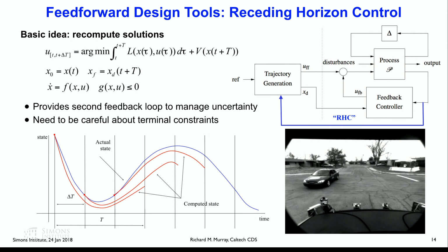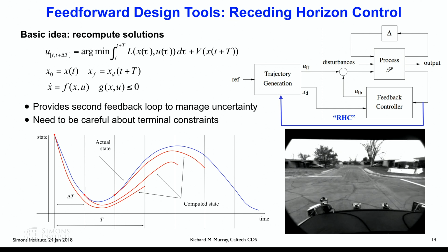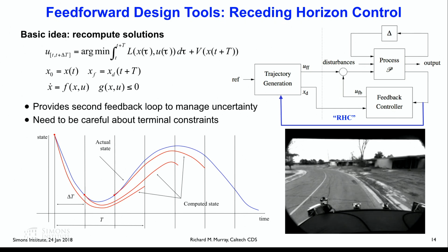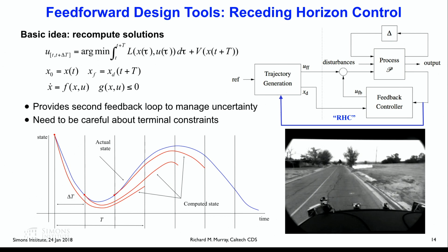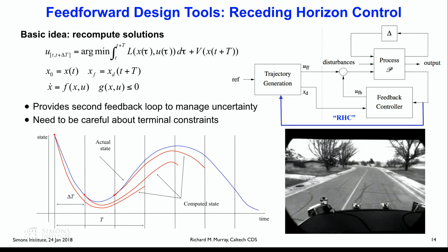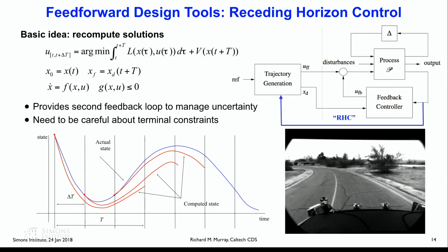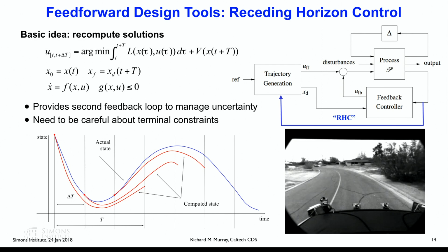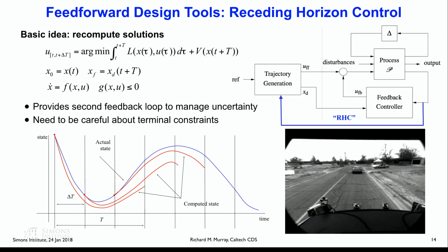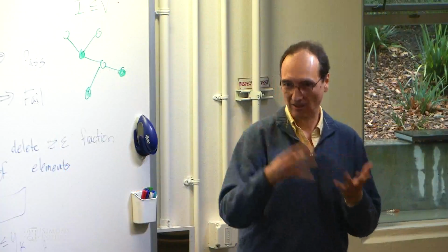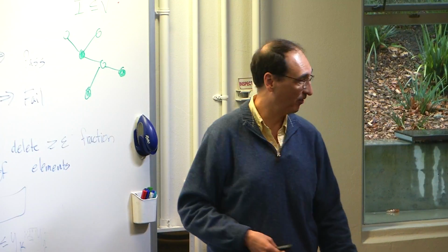Now there's other higher level stuff going on, but the trajectory generation part of this is saying, go down the road for as far as you can see, and here's the trajectory to follow. But every time I see a little bit more road, I calculate out what to do next. And if I don't quite follow the road, I also take that into account. So I'm just constantly recalculating this thing, again, at about 100 hertz for this particular system. Actually, it's between 10 and 100 hertz, depending on how complicated the obstacle set is and how long it takes the optimization to perform and other things.